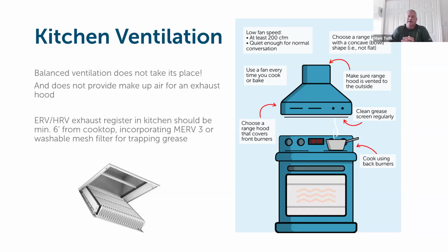They don't do that. I've had people argue, well, you can offset it and bring more air in than you take out. The manufacturer I work with allows 10% variance. So on a 100 CFM unit, you could bring in 10 CFM more than you're exhausting. But if you have 1,000 CFM makeup air hood, that does absolutely nothing. That's ridiculous. So anything over 400 CFM by code has to have makeup air.